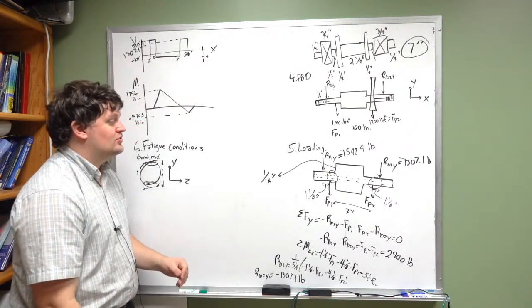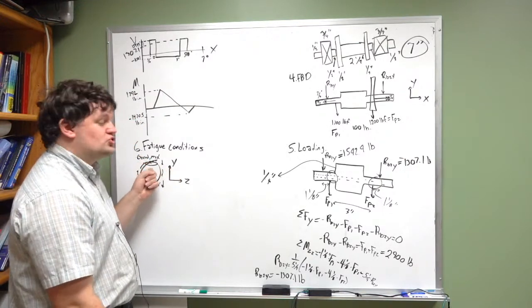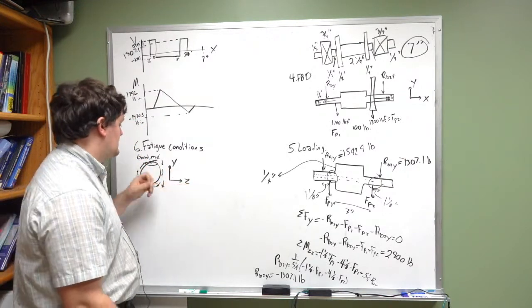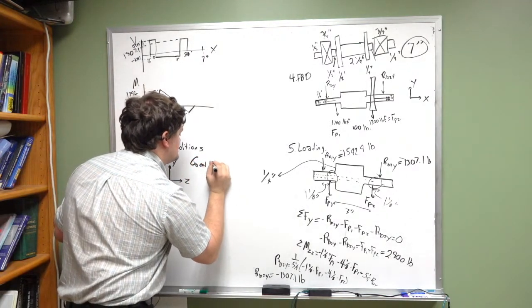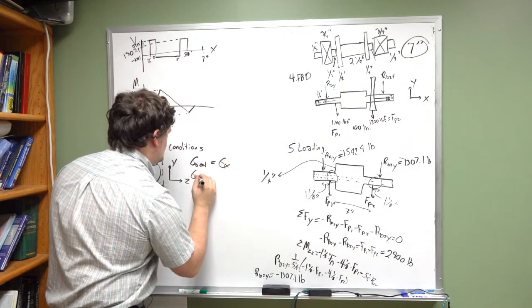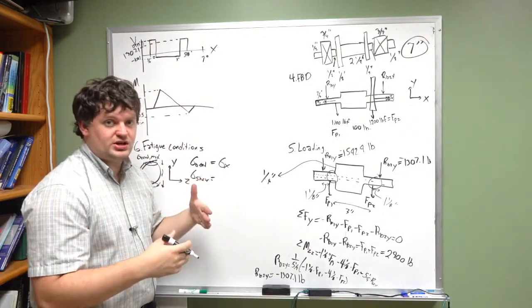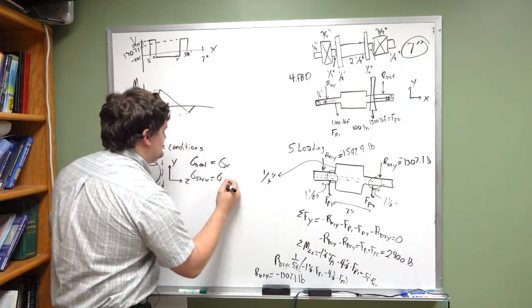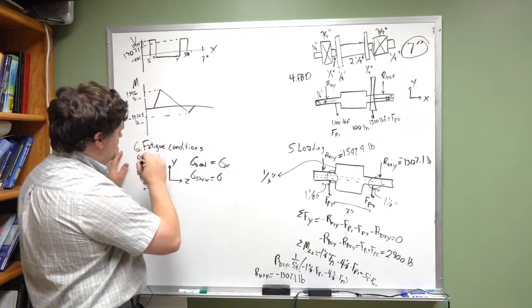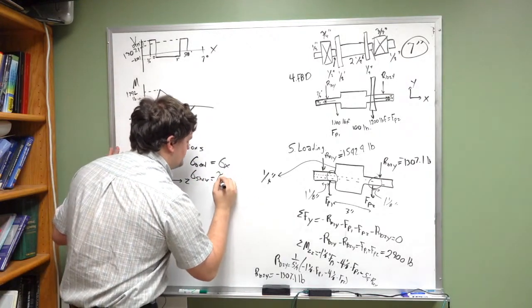When we have this loading, we only have one source of x directional stress. Okay, so we have sigma bend equal to a sigma x. We've got our sigma shear, because again, I'm just going through the loading conditions and what kind of stress they cause. This is going to be a sigma x. It's on the x face in the y direction, so it's not a sigma, it's a tau.